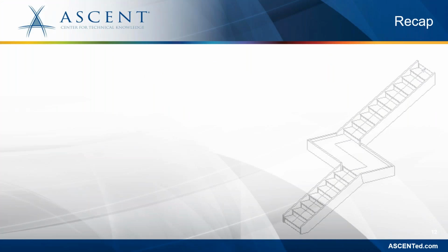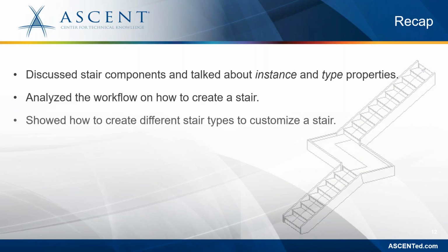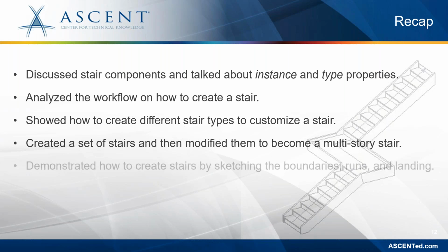And that concludes this webcast on stairs. To recap, we talked about what makes up a stair and looked at both instance and type properties. We talked about the workflow on how to create stairs and created different stair types. And I demonstrated how to create the single story stair, then modify it to become the multi-story stair, as well as the custom stair that was out in front of the building.